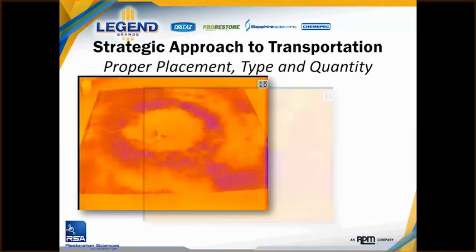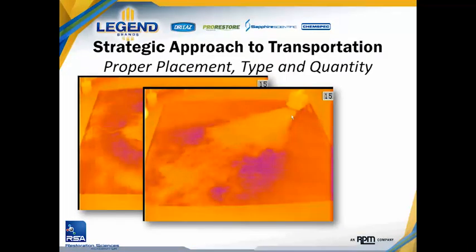When you move to a more common air mover in our industry, like the Sahara, you can see that its impact on air movement is very different. We have this zone immediately in front of the air mover, where the air movement is extremely rapid, extremely high in rate, and where that highest rate is, we've made the most impact. Then we get a bit further out from the air mover, and you can see we're still having an impact. There's still some drying occurring here, but the impact is not as substantial as where we had the higher velocity.